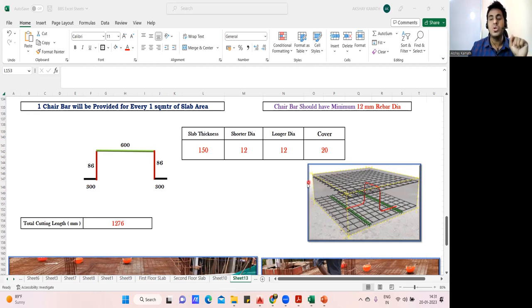Okay, fine. Good. So once this is done, next we'll find the cutting length of that. Now, two things you need to understand, there are certain constant values which you need to understand. So this length, whatever you can see, that is a top length, and practically it will usually be 600 mm. Okay, just remember the values. It will usually be 600 mm. So you'll ask me, sir, 600 from where did you take? No, I didn't take from anywhere. This is a general construction practice what we do.